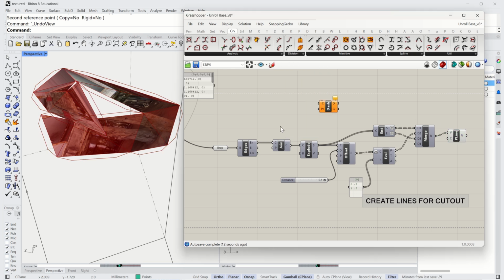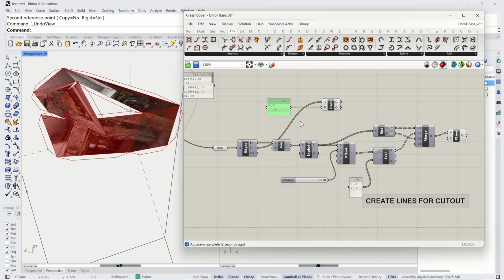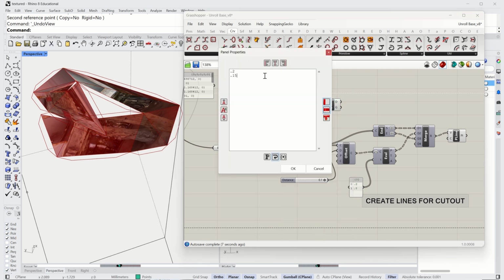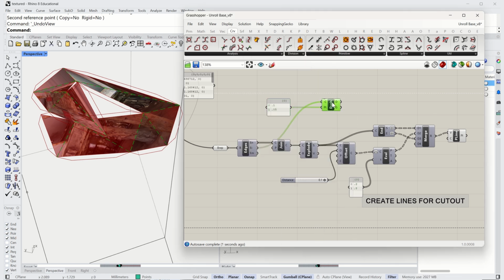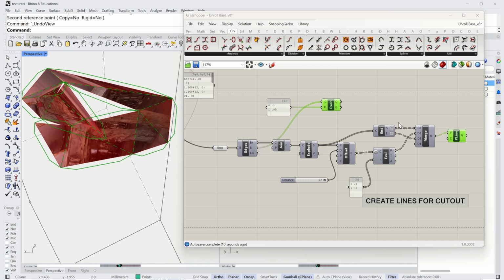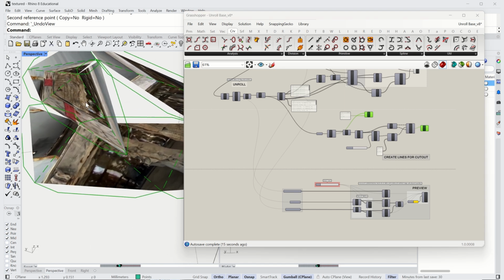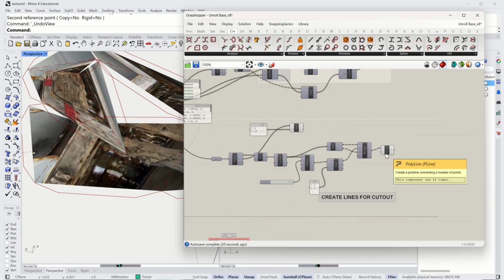The internal edges can be converted to a dashed pattern for laser cutting after printing. Depending on the geometry of the mesh, some manual adjustments may be needed, such as flipping over, rotating folds that were unrolled in the wrong direction, or splitting into separate parts to avoid overlaps in the physical model.